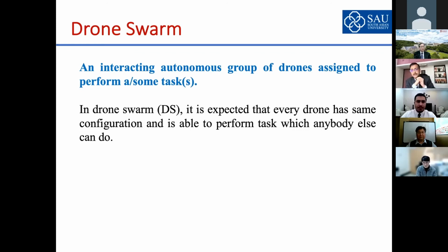Right now, of course, all kinds of sensors, networks and computing devices cannot be put on all the drones. It is very costly also, and the performance deteriorates. As soon as you increase the weight of the machine, the endurance will decrease. And so sometimes we assign certain tasks to certain drones, and other tasks to other drones.